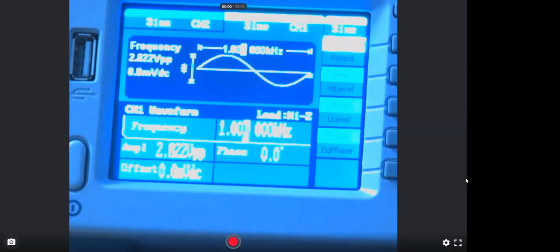In the lab, we basically threw number 4 out the window. And we're doing: adjust the amplitude to 1 volt RMS as read on your digital multimeter. Set the seconds per division control to 0.2 milliseconds per division.